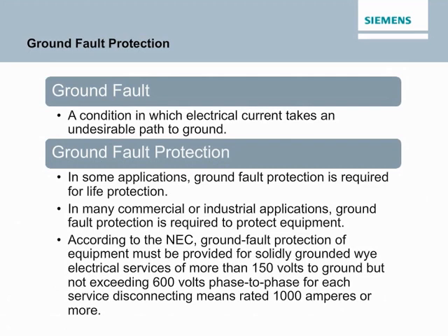A ground fault is a condition in which electrical current takes an undesirable path to ground. Typically, the current flows from a conductor to an adjacent grounded conductor or grounded surface. The most common type of ground fault is an arcing ground fault. In such cases, current often takes a high resistance path to ground and may flow intermittently or for a short duration. As a result, a ground fault often will not trip a circuit breaker unless it's been designed to sense ground faults. Nonetheless, ground faults can still be dangerous.